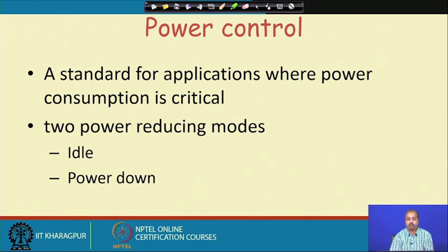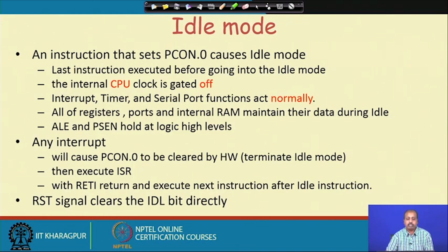Similarly, we have the 8051, any processor that you have now. If you look into it, you will find that some power control mechanism has been provided. So this 8051 also has this power control feature. It has one idle mode and a power down mode. In idle mode, an instruction that sets PCON.0 will put it into idle mode, and the last instruction executed